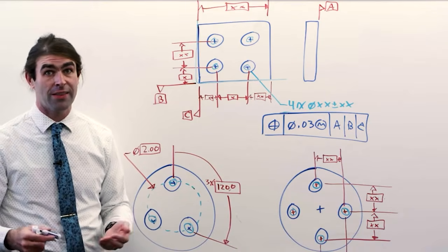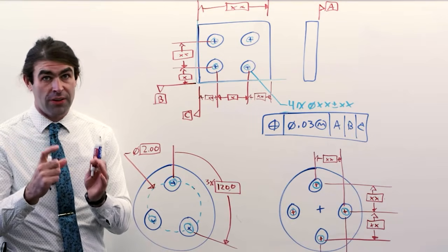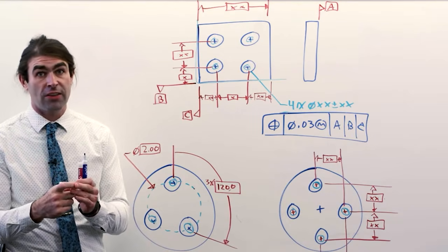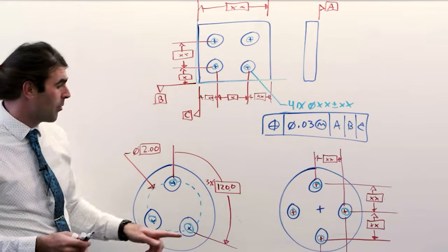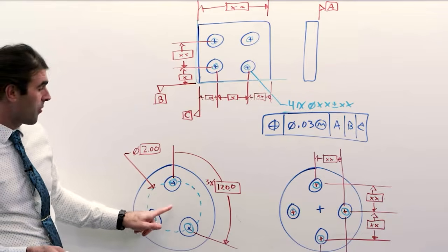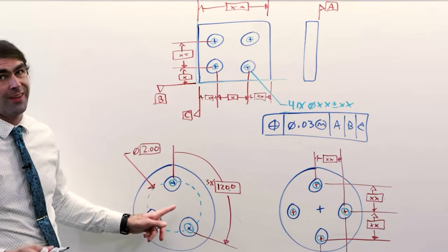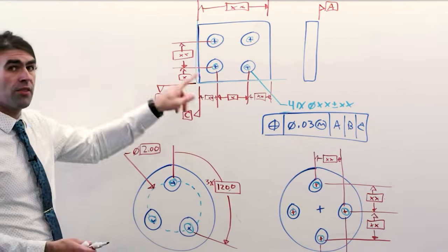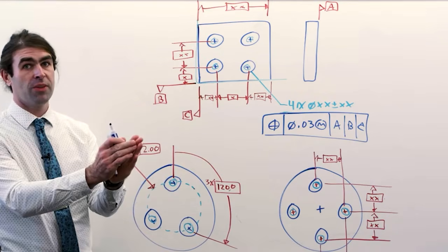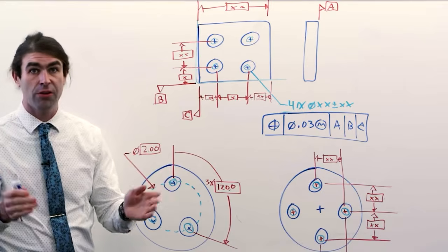So even way back then, they kind of recognized the wedge-shaped tolerance zone is not good. At least a square-shaped tolerance zone is better than that. The other problem with the angle is, the further you get away from the center, the further it can be off. For a simple part like this, it doesn't matter, but imagine you have a part with rings of holes. The further they get away from the center, the more they can be off in the angular direction.